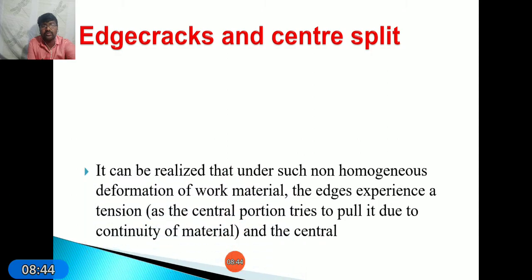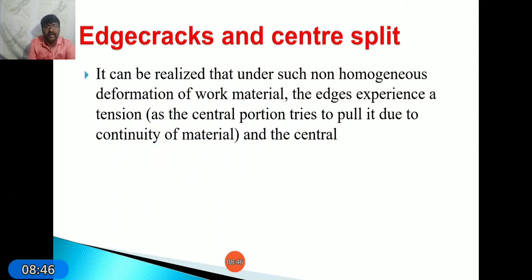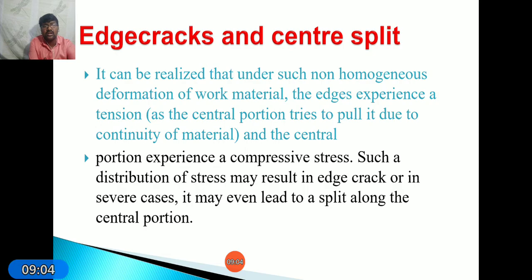It can be realized that under such non-homogeneous deformation of the work material, the edges experience tension, and due to the continuity of material, the central portion experiences compressive stress. Such a distribution of stress may result in edge cracks, or in severe cases, splitting along the central portion. These are the causes for edge cracks and center split.